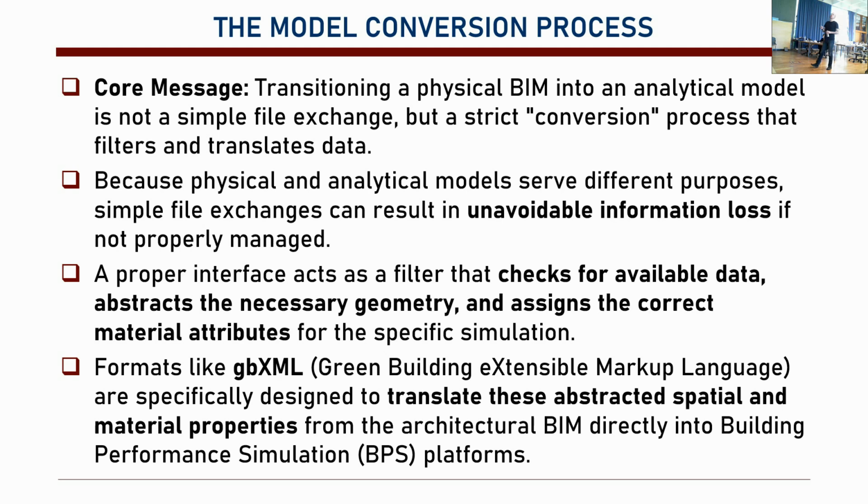We used to use GBXML, Green Building Extensible Markup Language, so that we can translate these buildings into abstract spaces and shapes, but it's not much used today because most of the simulation environments are integrated within Revit, within Forma, within many different software like ArchiCAD.